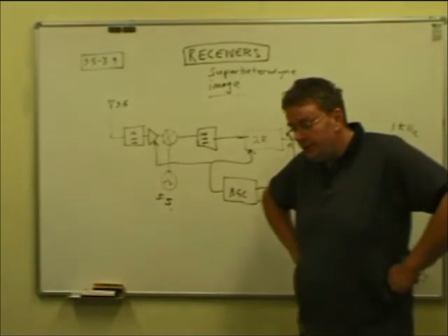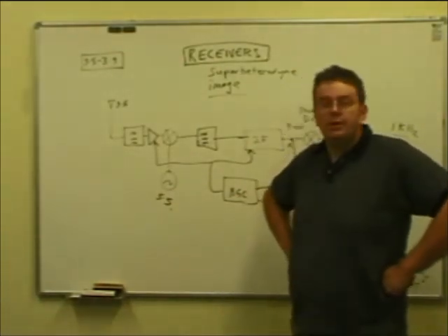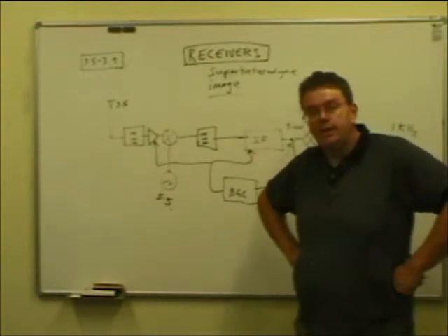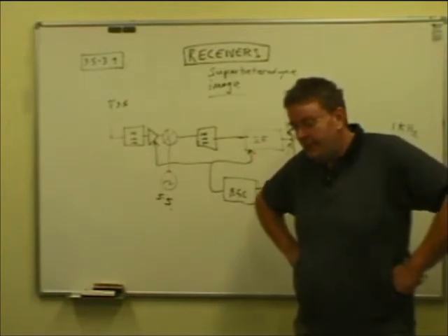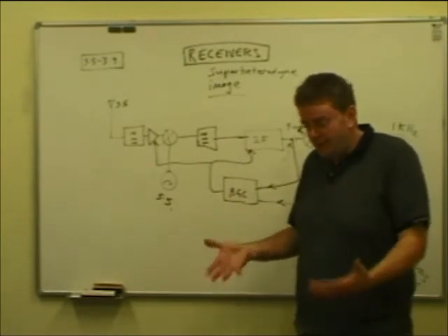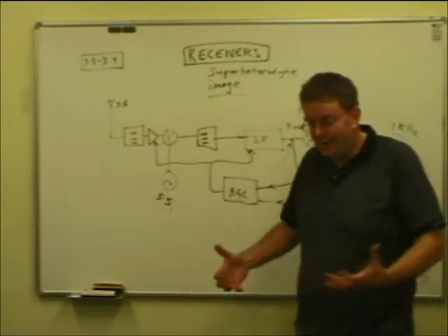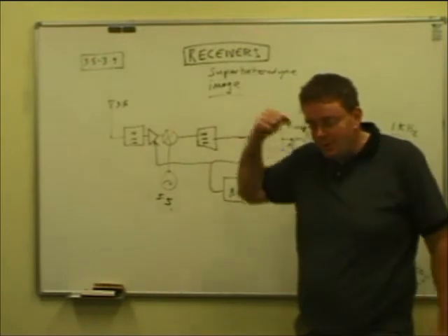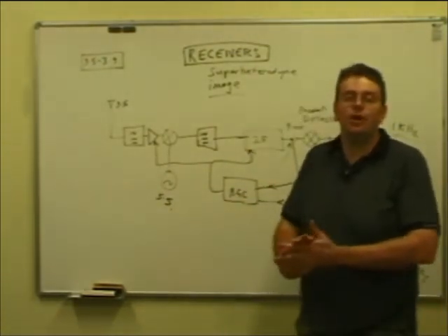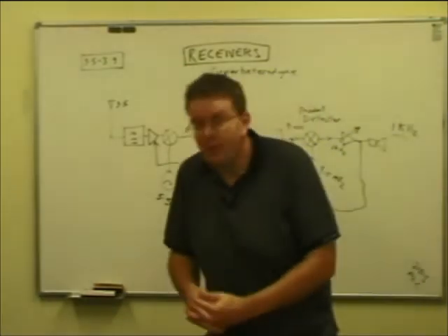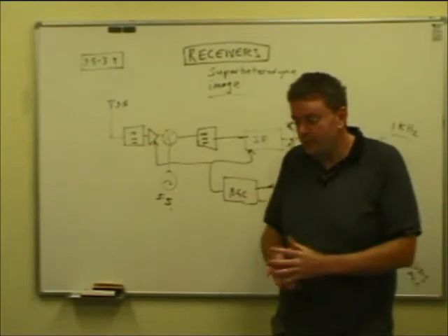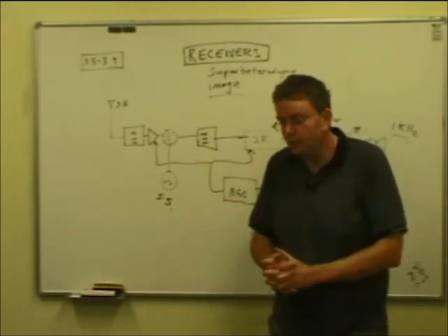With single sideband, when you stop talking and the amateur at the other end pauses for a second or so to think about what they're going to say next, maybe the weather or something like that, there's no signal coming in, there's nothing there, so the receiver will just crank the gain right up. And so then when they start talking again, bang, there's often a bit of what we call overshoot. The system takes a bit of time to respond to the signal, so you might get a sudden burst of loudness coming out of a loud sound signal before it brings it back under control.